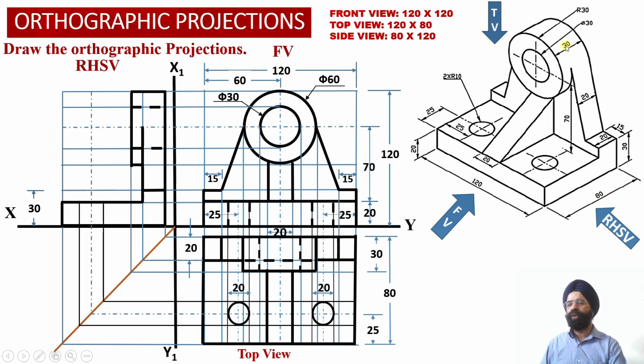And another thing we should remember, this circular hole again will not be visible to the observer from the right hand side. So we will be able to obtain dotted line or hidden line projections corresponding to this circular hole. From these two extreme points of the diameter, we have already drawn horizontal projector lines into the right hand side view. So now we can check this dotted projector line we have obtained corresponding to these two points of the diameter.